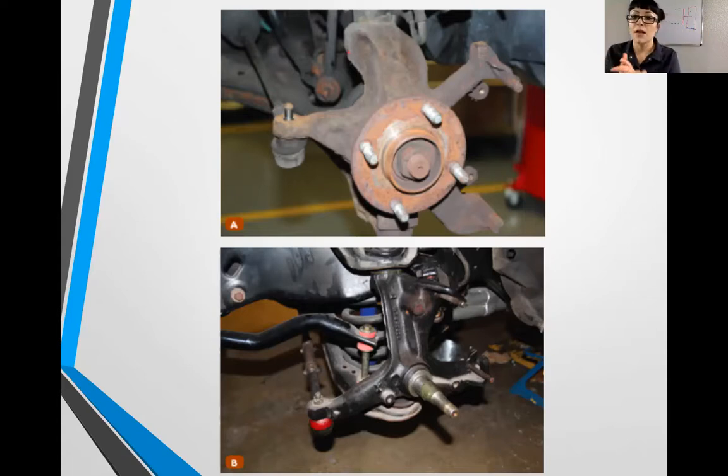Down here, I have to have a special type of brake assembly that has the wheel bearing inside of that. It's an integral design that we'll get into when we talk about brakes. Those are fixed rotors, while the top up here would use floating rotors. But down here, and this is the thing I really want you to pay attention to, this is called a knuckle. Down here, this is a knuckle as well, but this piece that hangs off, that's called a spindle.